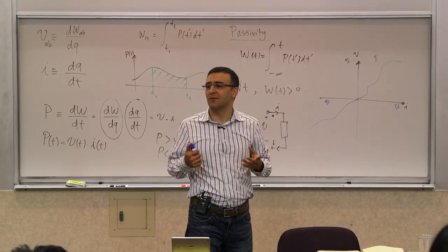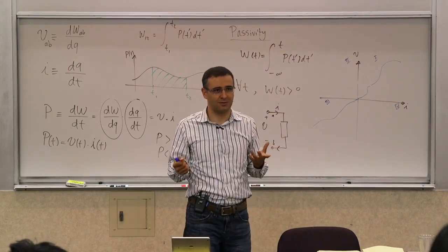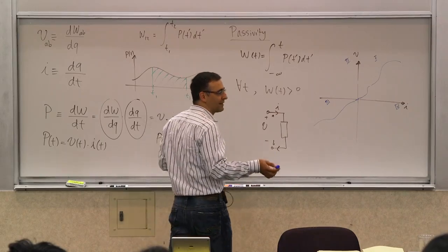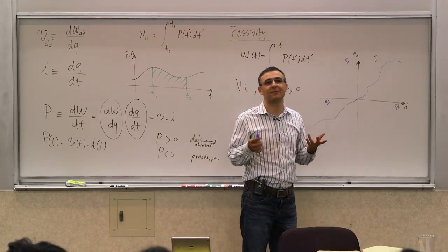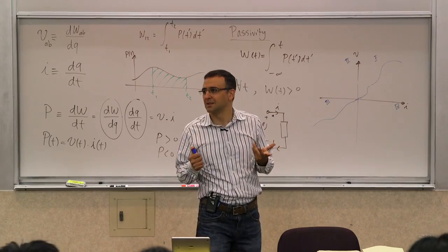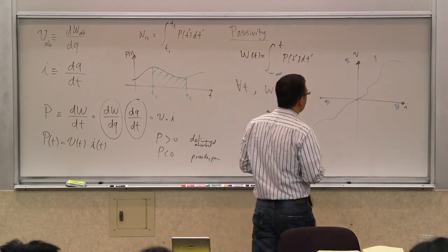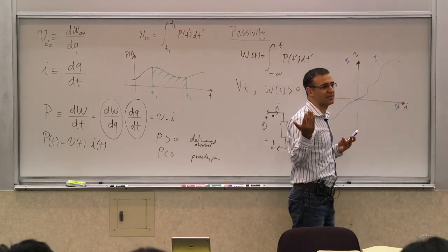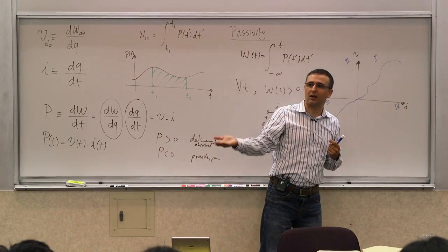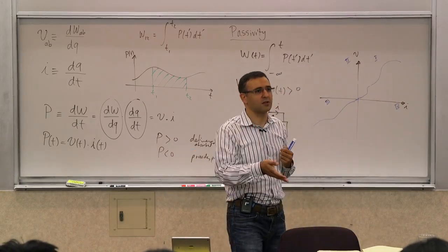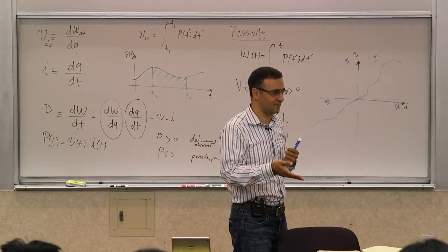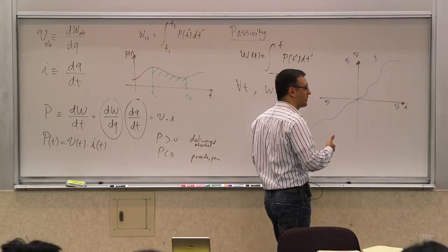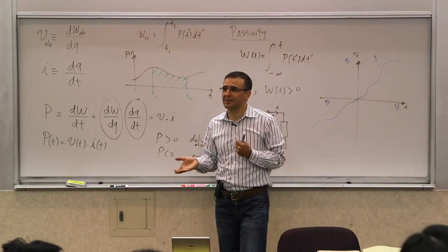We'll see that a capacitor is defined as a QV relationship, not an IV characteristic. And that's basically the fundamental definition of a capacitor. So these are the kinds of things that we generally call resistors, whose current is a function of its voltage, or its voltage is a function of its current. There are things whose charge is a function of their voltages, and those are called capacitors.